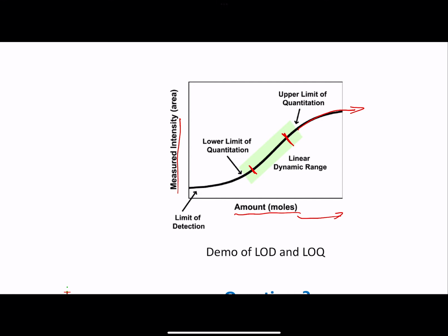If we have a calibration range here, and this is almost linear, but we have a signal that is very large, then it will be something here. But if we extrapolate our linear regression, we will have the concentration here. We can see there will be a very large difference. So once we have the calibration curve, we need to make sure the signal is inside our calibration range.